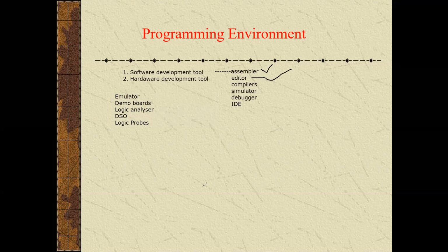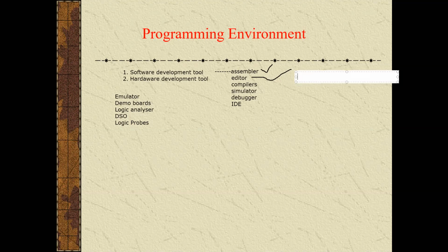Such kinds of instructions have some mnemonic, which represents the assembler. An assembler is a program which translates the assembly language mnemonics into corresponding binary code, and the assembler reads the source file more than once. So what can this assembler do? We will write an instruction such as MOV A, #30. This kind of instruction we are writing or editing in the editor.